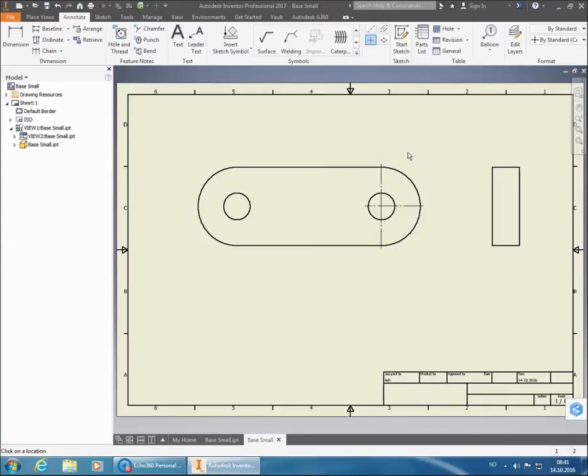On the other side, I can show what happens if we only click on the hole. So if I only click on the hole, my lines won't extend all the way outside the parts for the curved edge there. So that's why I also select the curved edge. Because now there is no way of misinterpreting this, because we have a center mark that shows the hole, and it is in the exact same location as the center mark that is showing the curved edges, which means that they share the same center line, so that they're placed on the exact same point.